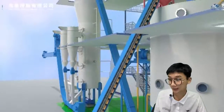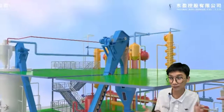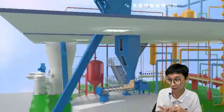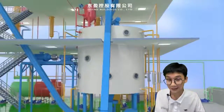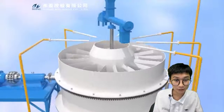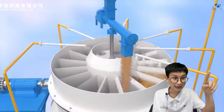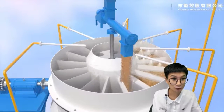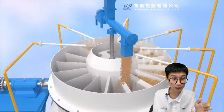So this is the elevator to transport all of the oil seeds. Before this part, we have several machines to deal with the oil seeds, like removing impurities or pressing, a lot of different machines. And this one is our extractor. All of the oil seeds will get to the extractor, just like this. As you can see, this yellow pipe sprays the hexane directly onto the oil seeds.